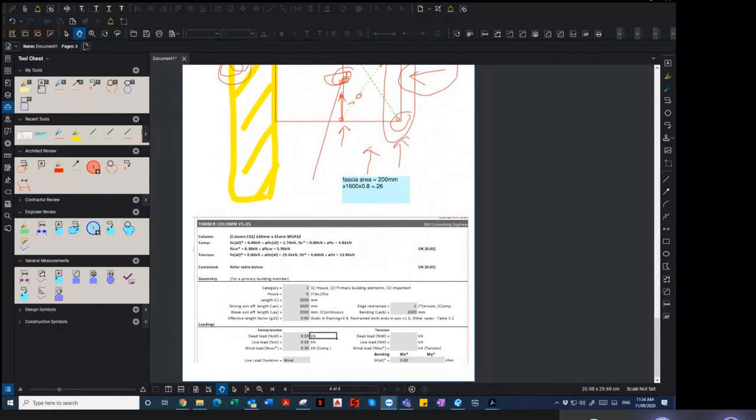Perfect. What's your force over here, the angle force which is transferred to the member, the bracing? I had 1.29. How did you get 1.29? Oh, because you had a gable roof, isn't it? Yeah, it's a 30 degrees pitch in there.